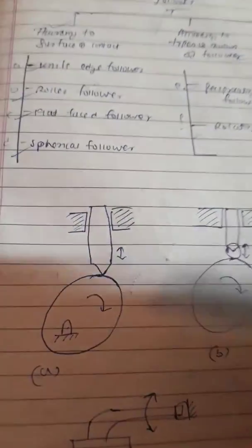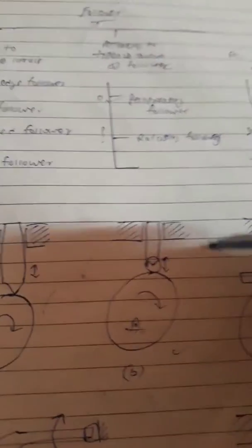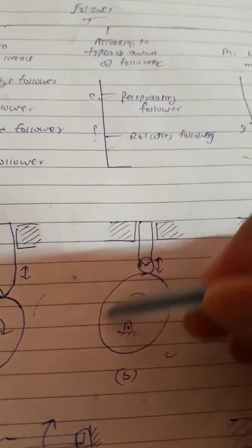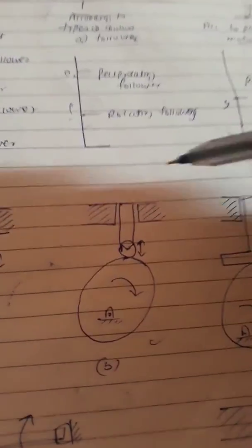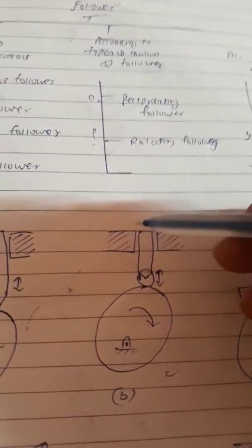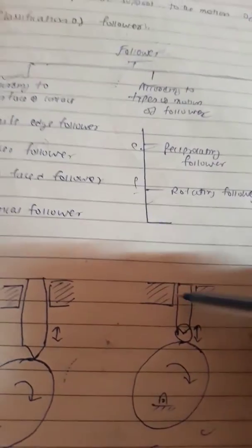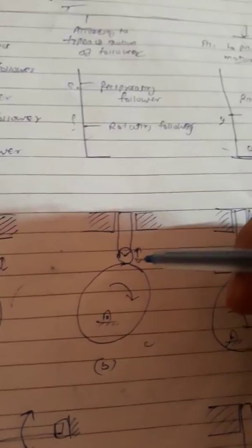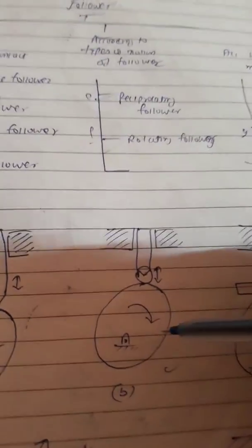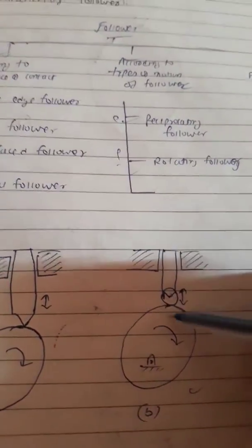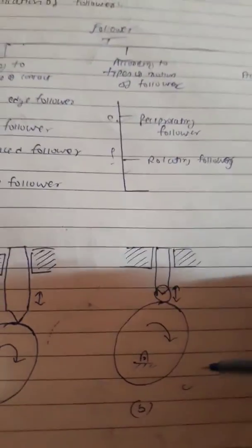So we designed the roller follower, where the knife edge is connected to a roller and then the cam. Here we can reduce the wear produced by the knife edge, but the same problem of thrust between the follower and the frame remains. Even in this, sliding is a problem because both are rotating parts, so at high speed there is sliding.